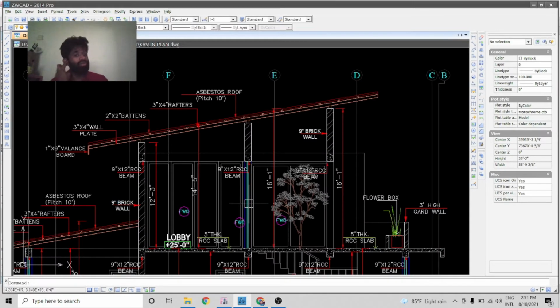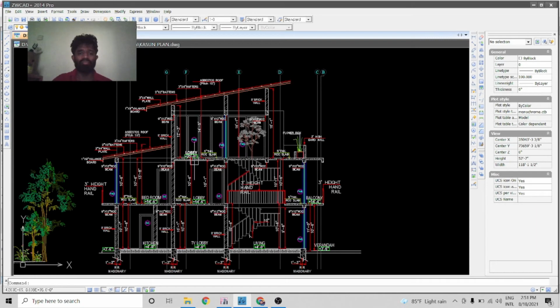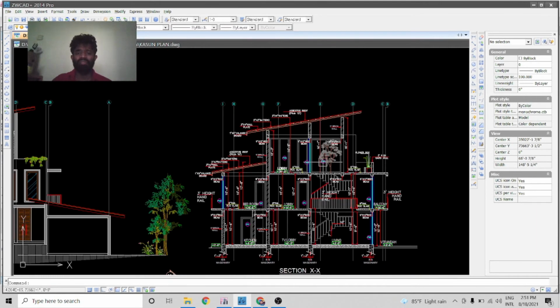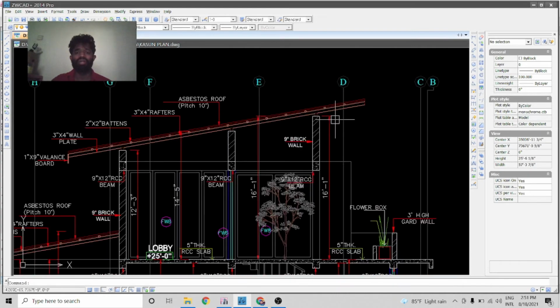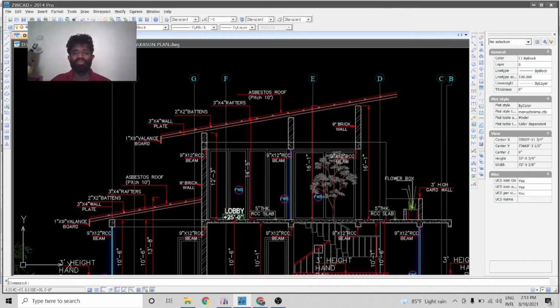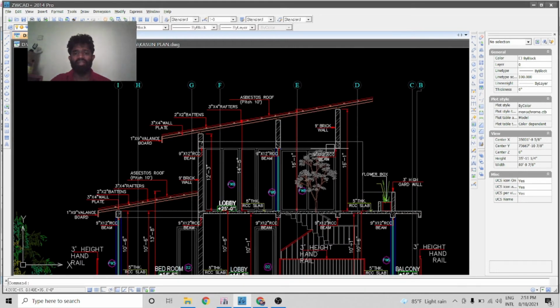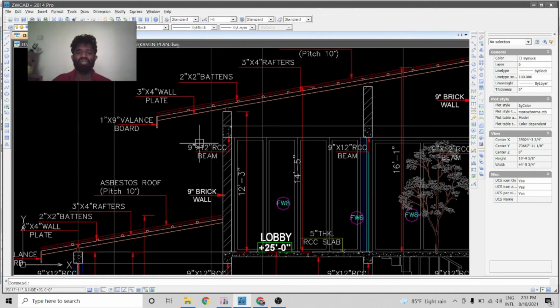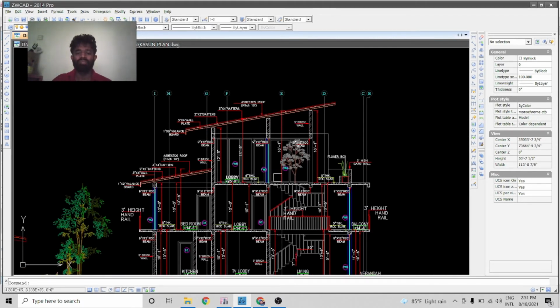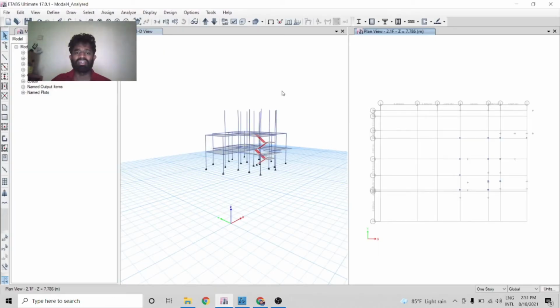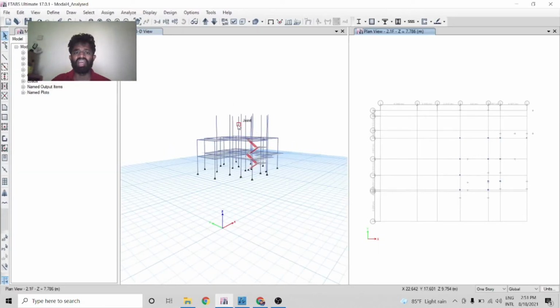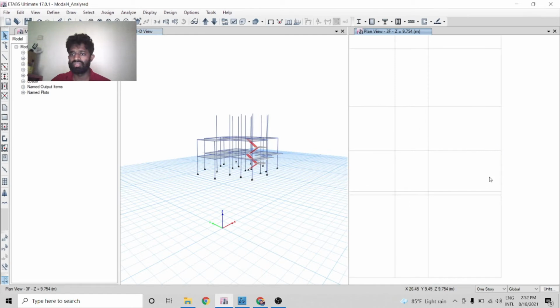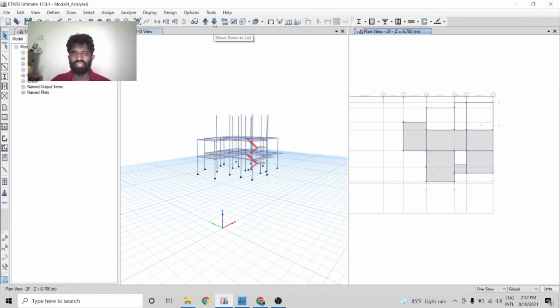We have two slabs now. For this roof terrace slab, they will produce a roof for this one. So the columns go to that level, but in this level we can produce a roof beam. We can say use 9 inch by 9 inch RCC beams for this one for time purposes. So we have to apply it inside the model. Our columns are freely waving on the top.